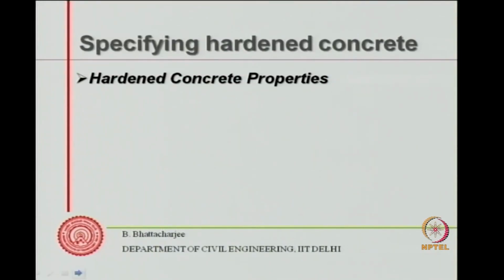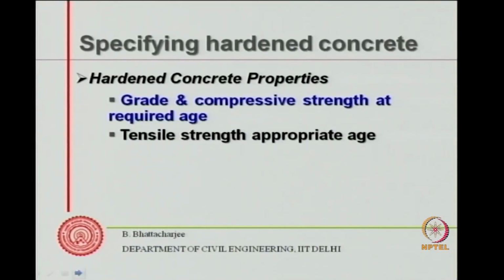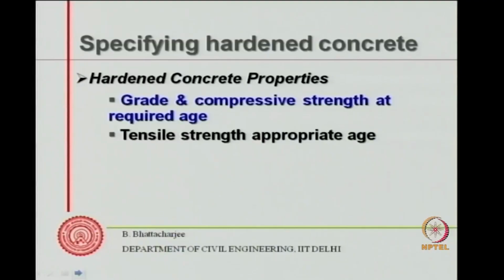Hardened concrete. Since concrete is a structural material, we specify the grade of concrete in terms of its compressive strength at a certain age, because in module 1 we have seen that the reaction of cement with water produces a material which is stone-like, but the formation of this hardened material from a plastic state takes time. First it solidifies, and then gradually it gains strength. And this process of strength gain takes time, quite often could be months.